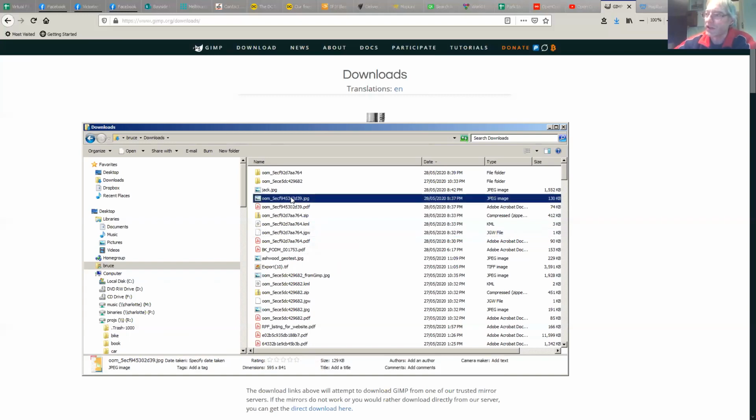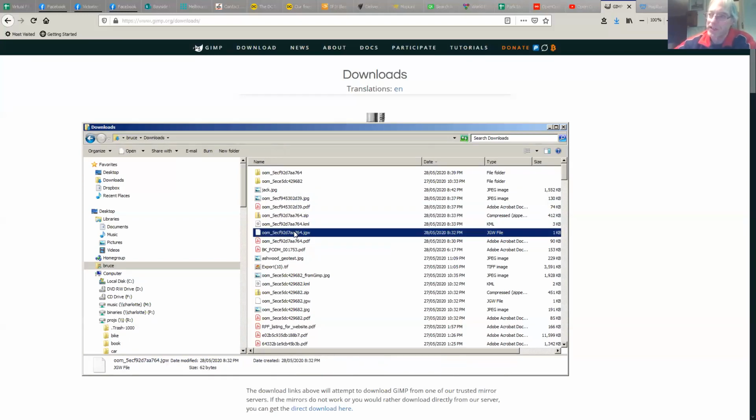Basically, you click on the JPEG in Open Orienteering Mapper, and you say, I want the georeferencing information from the world file, and it sees that file as long as it's got the same name in the same directory, and it will pull in the georeferencing information for you. So the map which you pull in from OpenMap will be georeferenced in OCAD or Open Orienteering Mapper.